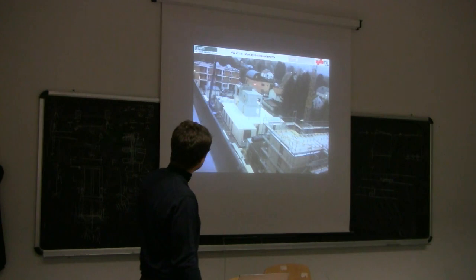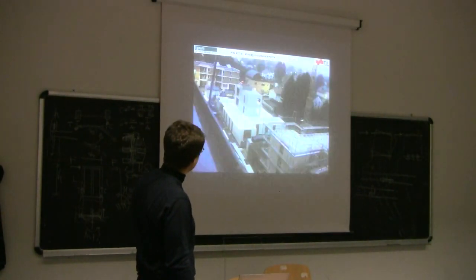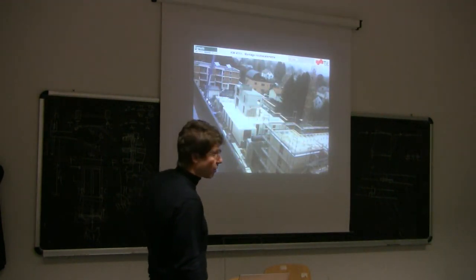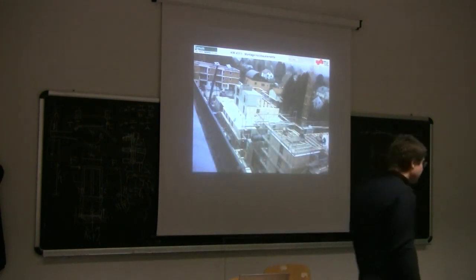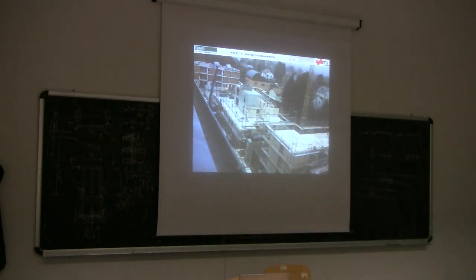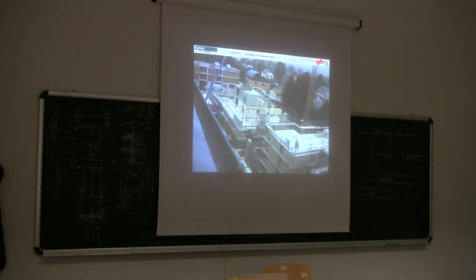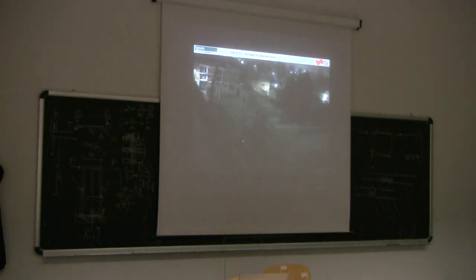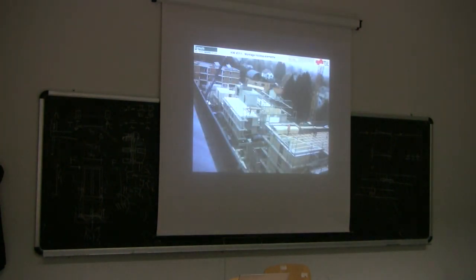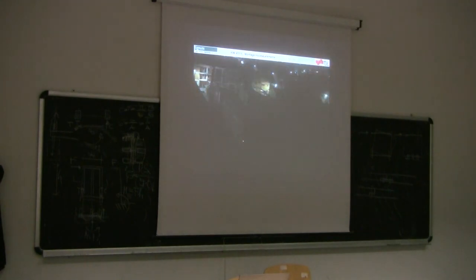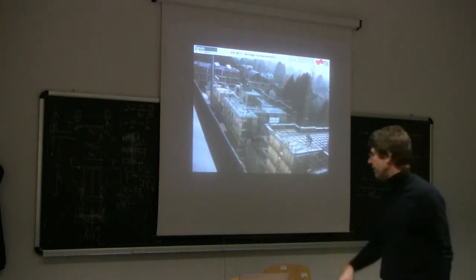You can see that in this case there is a lift and stair shaft made of reinforced concrete. Why is that? Because in Austria, so far, there is a fire regulation which does not allow combustible structures in the egress system, which means in the escape routes, the staircase and lift shaft. In Italy, such a regulation does not exist. So in Italy, if you want, we can build the whole building out of wood without the need to have a part made of reinforced concrete.